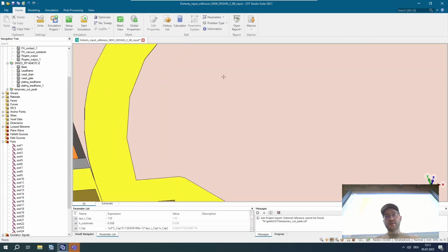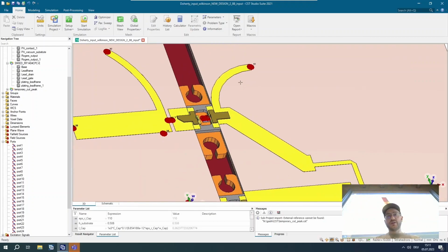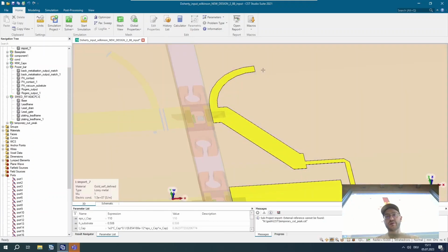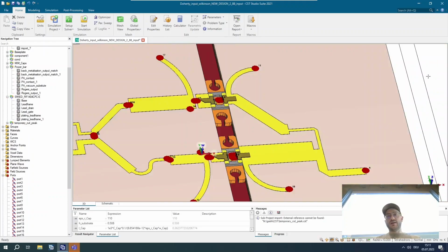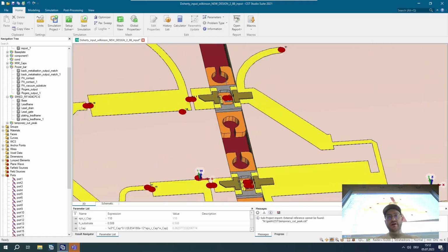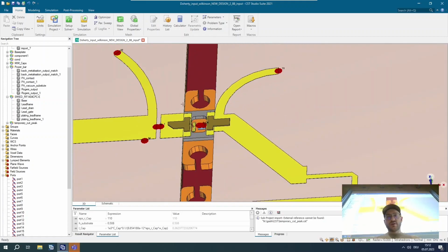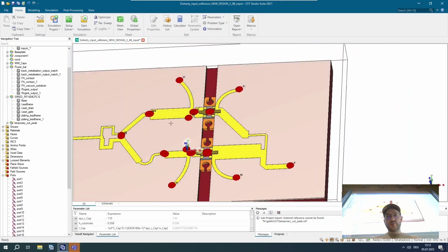Then later on in ADS, you connect this microstrip line to a separate LC network, to an RF shunt, and so forth, to be able to have the respective bias that you need to apply to it. This is the gate bias, the drain bias. As I said, you need a bias voltage to apply to it. And then you have the respective matching networks.